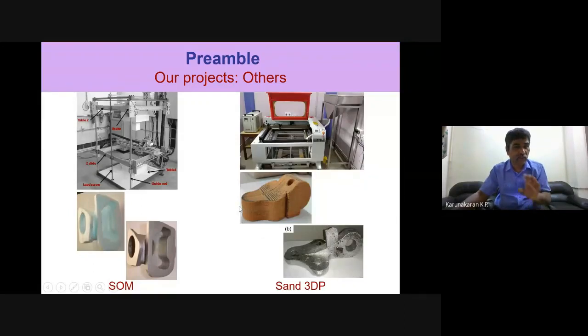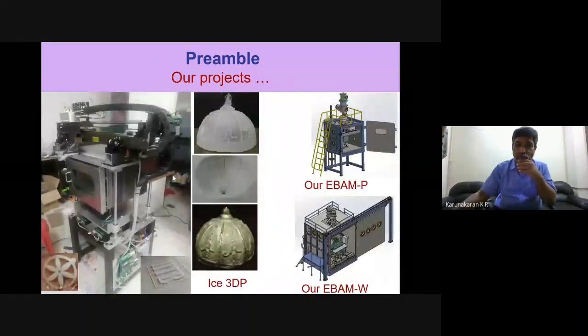You see that when you say sand mold, immediately poor accuracy comes to our mind, and a rectangular or cylindrical block of mold comes to our mind. Here you see that we have a conformal mold. It has 2 advantages. One is the building cost comes down. Second is during the solidification, the heat transfer also will be very uniform. So a lot of disruptive benefits are coming through these technologies.